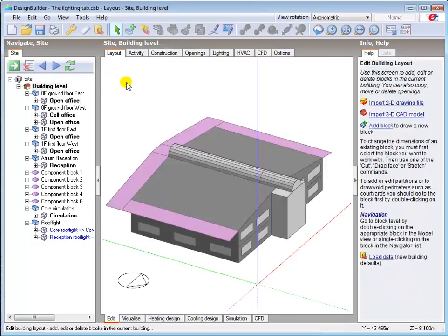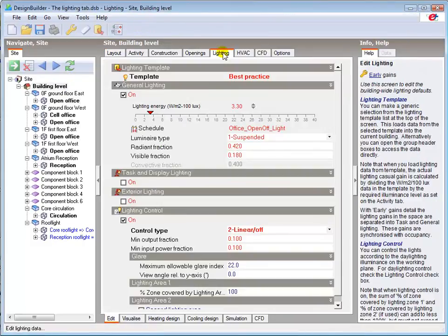Specifying 2 daylight control areas enables you to use different sensors to control the front and back areas of deeper plan zones, or where you have different daylight illuminance levels at any one time, created, for example, by external glazing on one side of a zone and internal glazing from an atrium on the other.